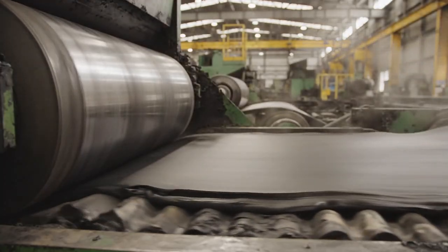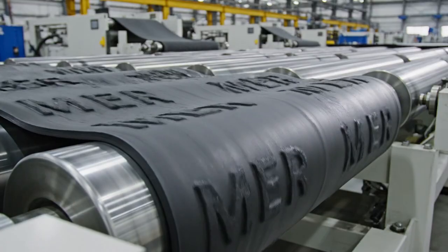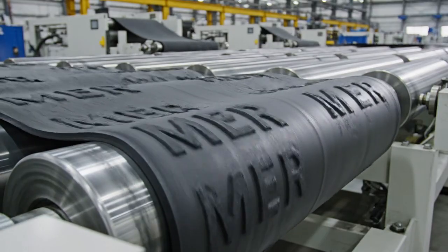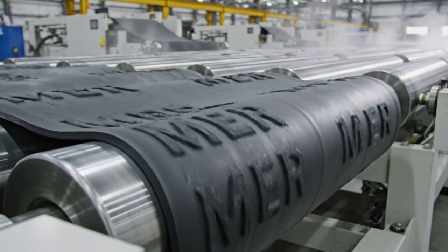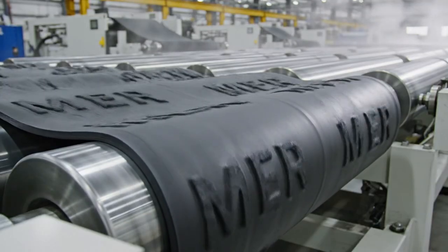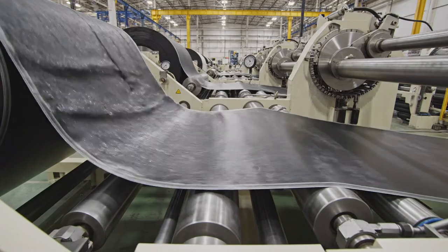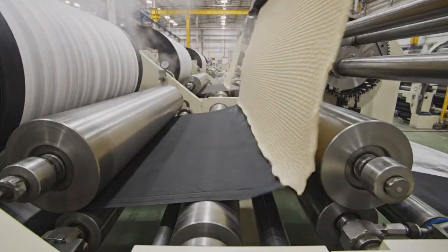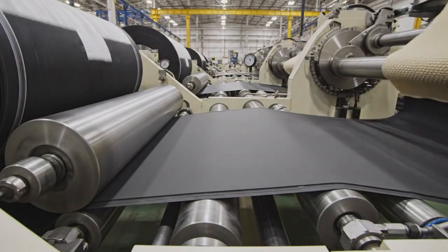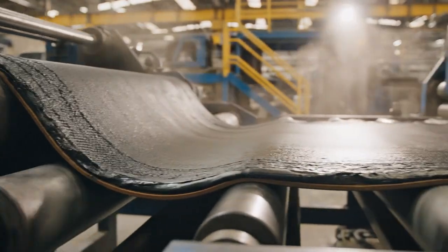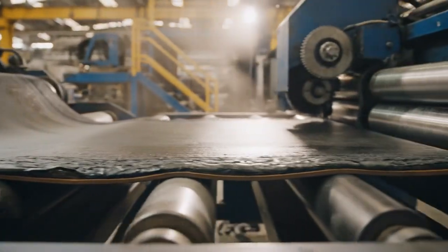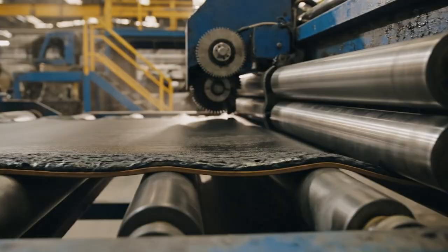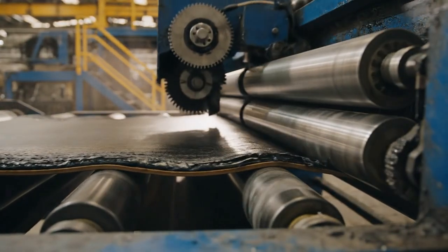There are different formulations for different parts of the tire. However, in each case, the result is gummy rubber dough, which machinery rolls into sheets to await further kneading and processing. With a corded ply, polyester unrolls into a machine called a calender. The calender is equipped with rollers that apply warm rubber to both sides of the fabric. This produces a rubberized fabric that will be used to reinforce the tire.